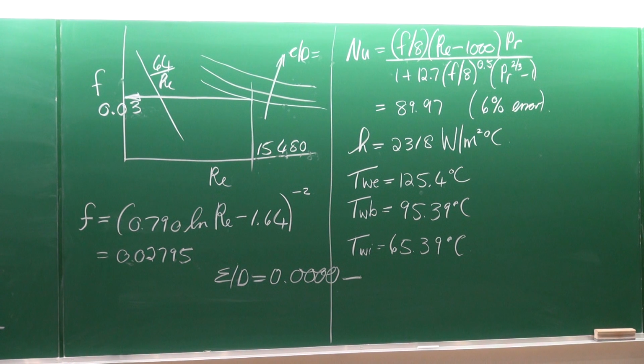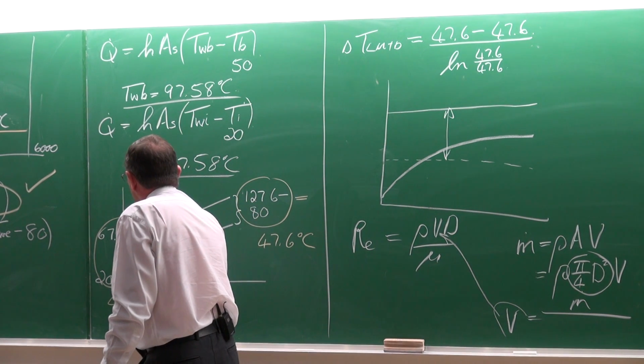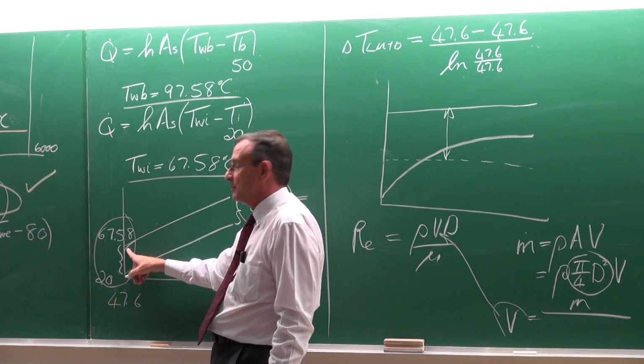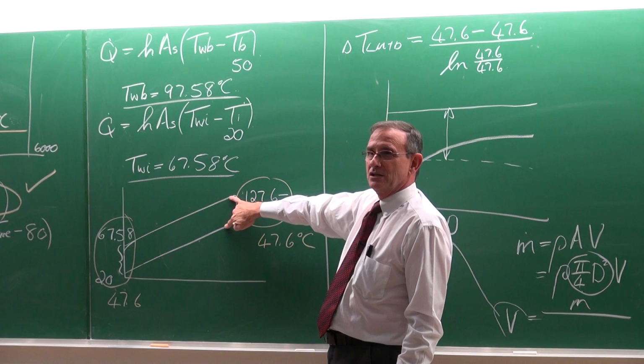You've got another question? When you work out your heat transfer coefficient, the debate was that it was manageable, that it was so long. But if you had to use the LMTD method, technically the temperature difference would be slightly less. So the question was, if you take into consideration that the first part is developing, can you use the LMTD? I think so. I think you can try it.